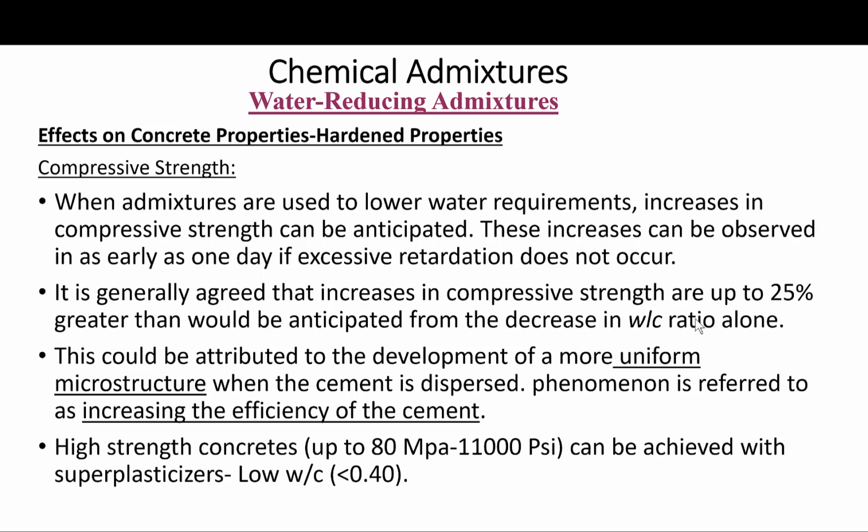When used at low water cement ratios, superplasticizers can modify type 1 cement to behave as super high early strength cement, exceeding even the strength gain of a type 3 cement. So imagine, when we remember what we said before, sometimes there are other substitutes to using different types of cements.